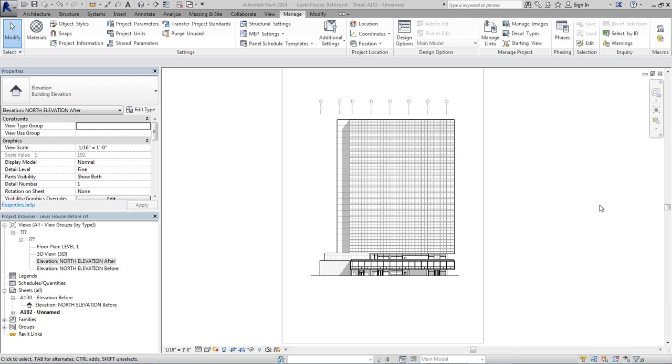What's interesting is that I quickly mentioned that every year, getting CAD two-dimensional data in and out of Revit gets a little bit better, which suggests that it still doesn't work perfectly. So doing it with 3D, you have to be much more careful, and you've got to work out that workflow before you invest a lot of time developing stuff in CAD. Because for the most part, if you bring 3D information into Revit, it's pretty much dead geometry. Unless you're applying some sort of Revit geometry to it, it's really not that useful.